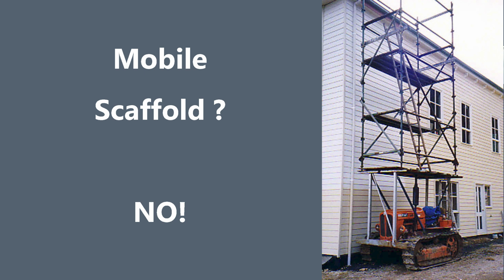This guy here, he wanted a mobile scaffold. Problem is, what people don't understand, if you move a scaffold, it has to be re-inspected every time you move it. So we got some issues. Plus construction on this. You got fall hazards. Okay, it's not fully planked. You do have a ladder there, but how do you get up on top of the mobile part? I mean, all this is wrong.